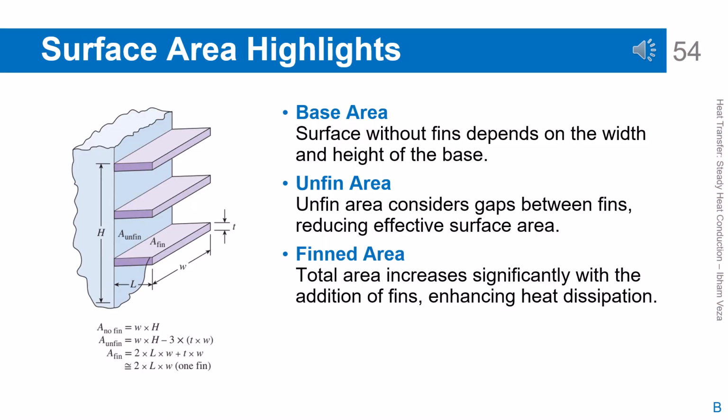Surface area highlights. The base area without fins is determined by the geometric dimensions of the main surface. When fins are added, some area remains uncovered and is called the unfin area. The total surface area increases drastically due to the contribution of fin surfaces. This increase in area is the main source of enhanced heat transfer. Therefore, surface area calculations must be done carefully.